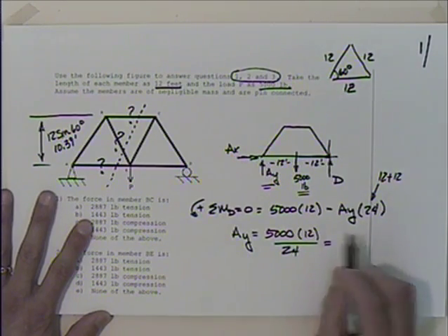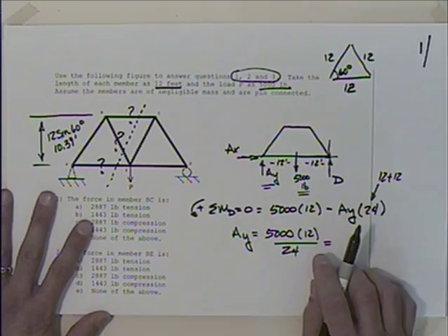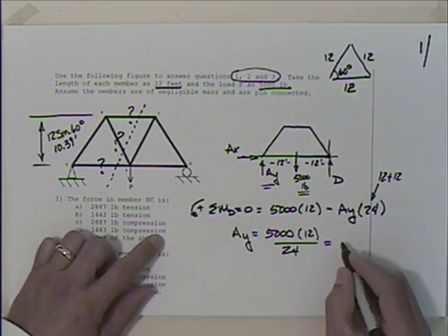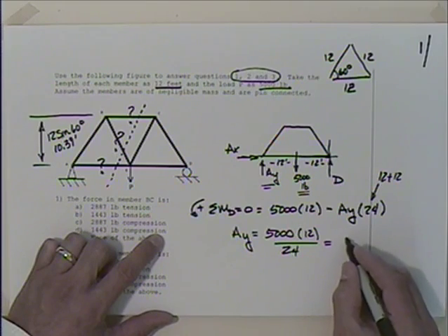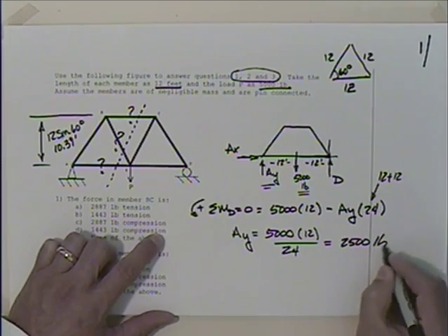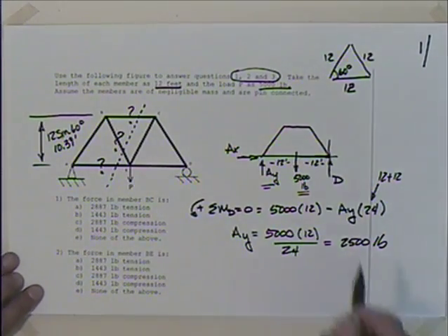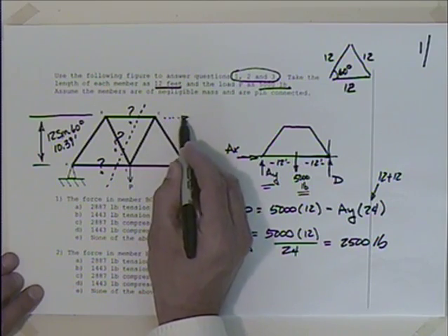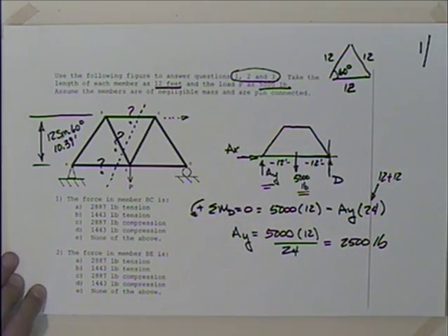And a lot of you looking at the symmetry of the problem, the symmetry of the loading, the symmetry of the members would recognize that that's just half of 5,000, 2,500 pounds. Now, had someone come up here and put a force off of it up here like that, then that wouldn't be true at all, or had different geometry, that may not be true at all.